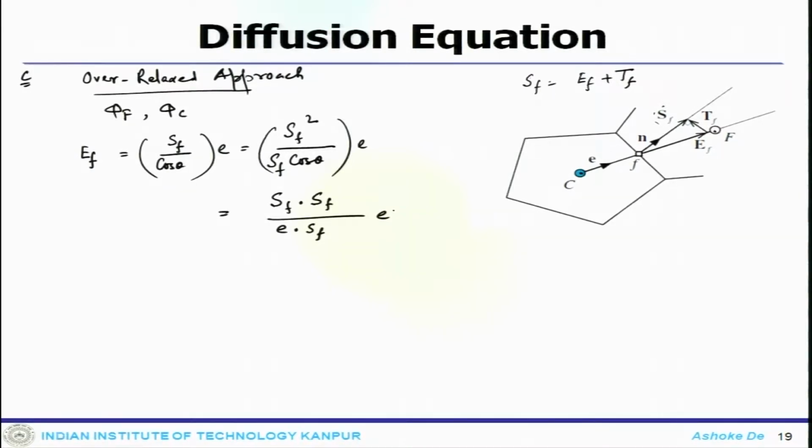To summarize what we are doing here, the diffusion flux at an element face of a non-orthogonal grid cannot be written solely in terms of the values at the nodes connected through the cell centers.